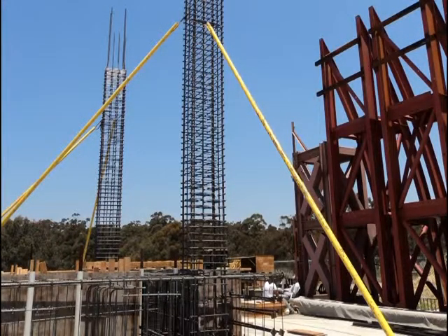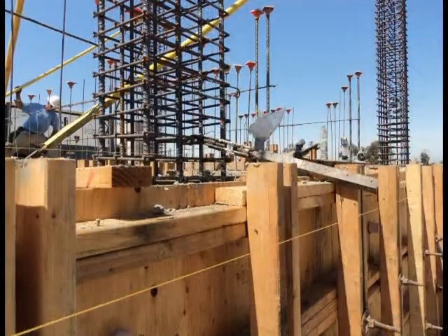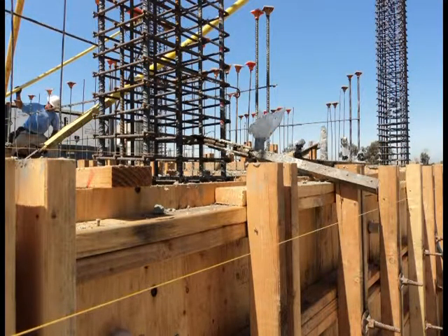Typically, reinforced concrete columns are detailed such that a nominal amount of cover concrete is provided between the edge of the cross-section and the reinforcing steel. This concrete cover is measured from the outside face of the column to the first longitudinal reinforcing bar and based on American Concrete Institute standards. Concrete cover is used to protect the reinforcing bar from environmental effects such as water intrusion, which may cause corrosion, or to protect against extreme situations such as fire, both of which would weaken the steel reinforcing bars.